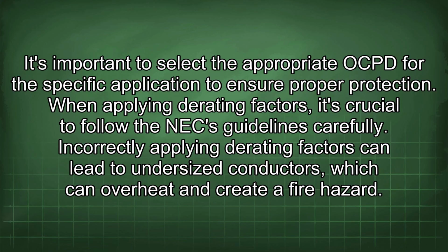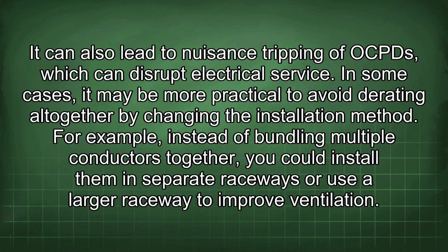When applying derating factors, it's crucial to follow the NEC guidelines carefully. Incorrectly applying derating factors can lead to undersized conductors, which can overheat and create a fire hazard. It can also lead to nuisance tripping of OCPDs, which can disrupt electrical service.